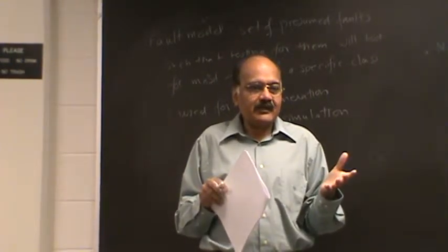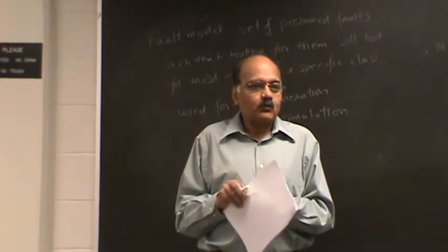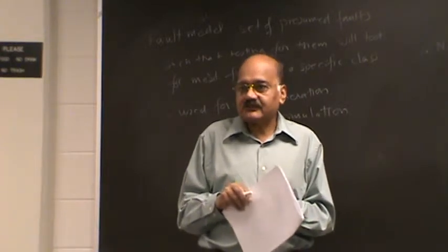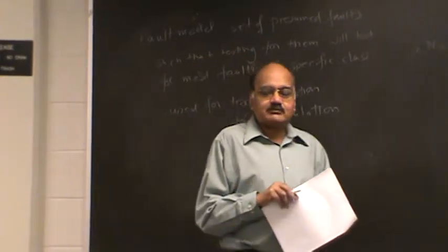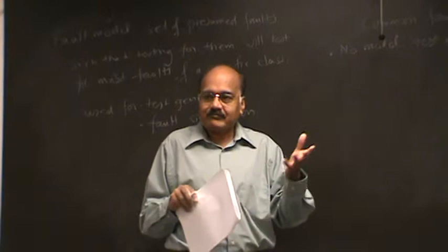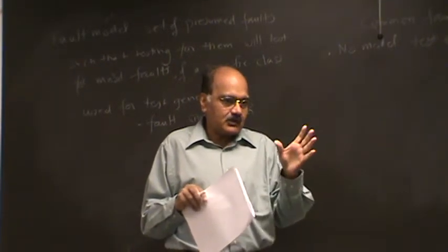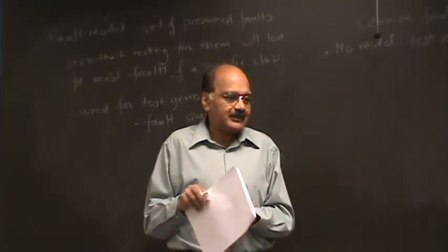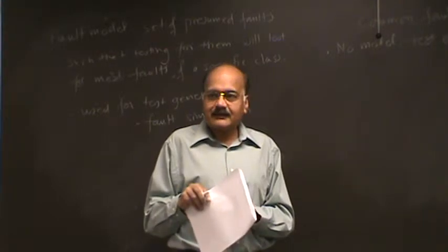And usually exhaustive testing will not be the best choice. But in some cases it may be okay. If it is a small circuit, a small combinational block, you can apply all possible combinations, and that could be feasible.